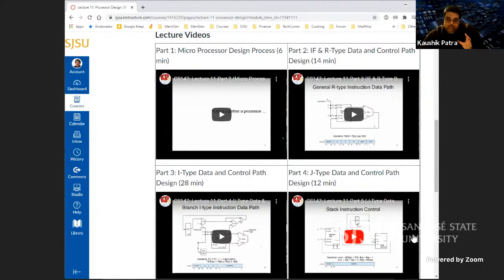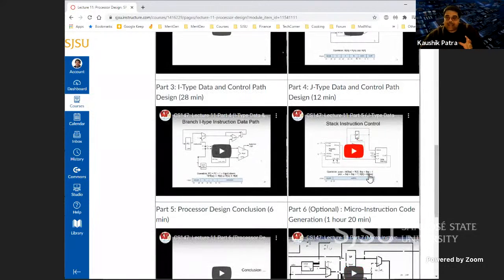So once we understand that, then we actually put together these three-part circuits on top of each other and optimize them. We don't need 3 ALUs, we don't need 3 register files and so on and so forth. We just make it into one big circuit, using many multiplexers around this data path at least.